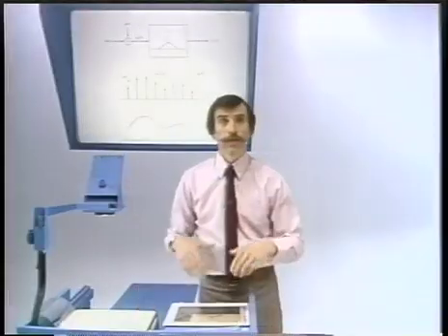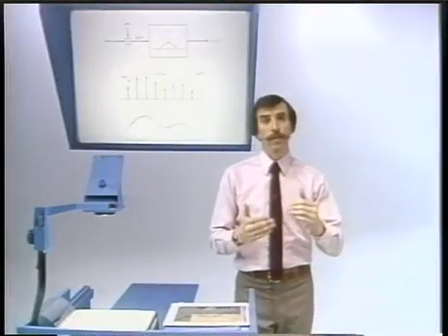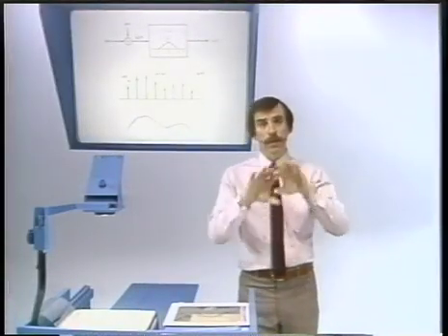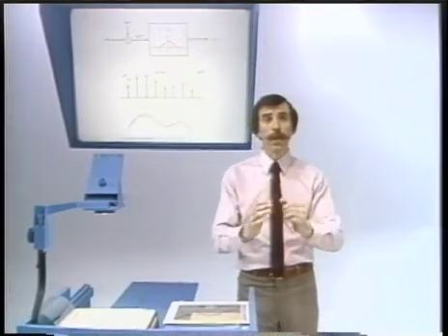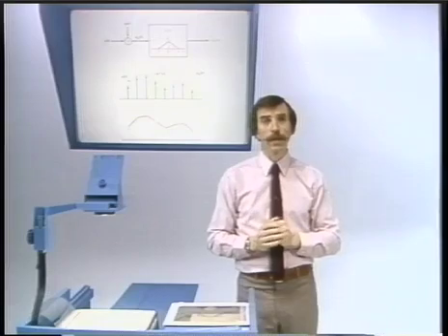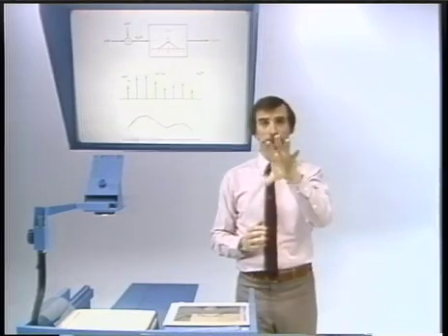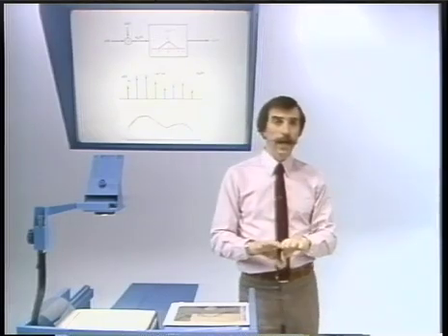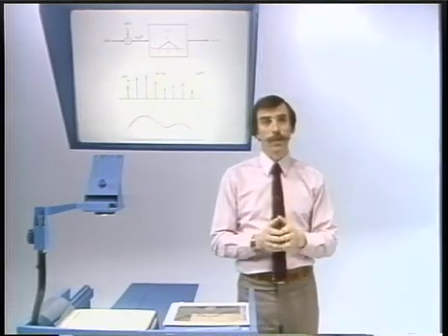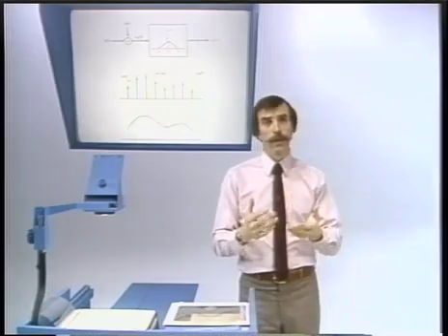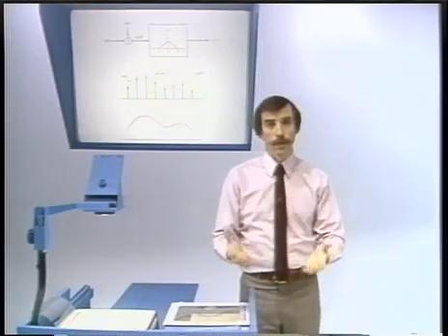So now let's again look at that, remembering that at the top we'll see the original continuous curve, exactly the one that we had before. Below it, the set of samples together with the impulse response moving along, and then finally below that, the accumulation of those impulse responses, or equivalently the convolution, or equivalently the reconstruction.